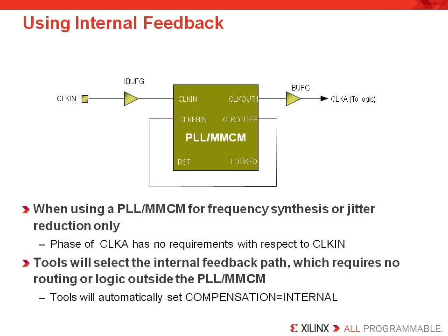All of this means that crossing between two clock domains can be accomplished synchronously and can be described with simple timing constraints. In fact, if a timing constraint is placed on the input clock to this PLL or DCM, the implementation tools will automatically analyze the timing requirements for signals that cross between the two output clock domains.